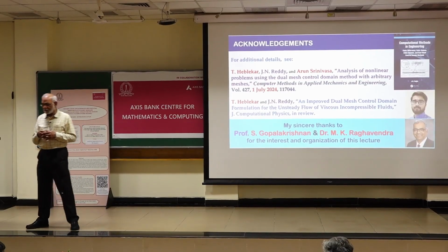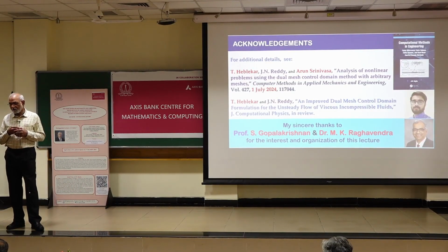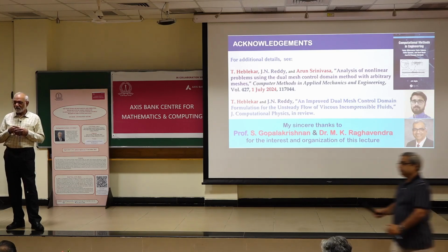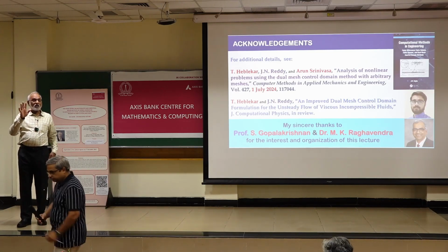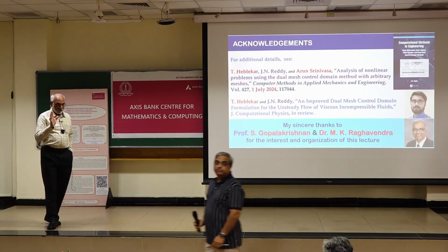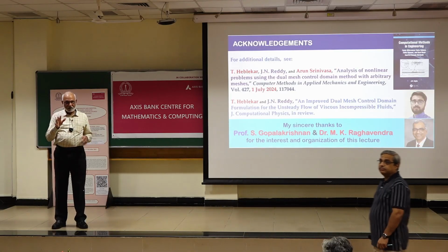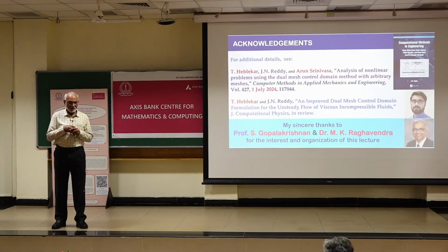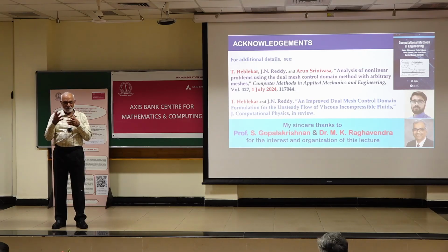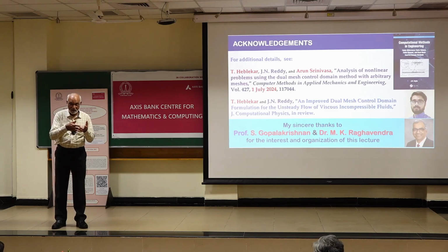Just a quick question: do you have the same issue with interpolation, locking, and others? Excellent question. Remember, when we think of all these methods, they don't bring locking. It's the interpolation that brings locking. If you really have two or more variables in a problem, and those variables are not the same, it's not like elasticity where all variables are displacements.